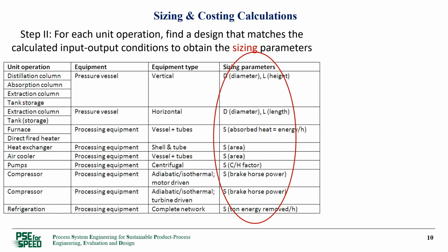So we need models then to calculate them. Some simulators give some of these design parameters. Usually the column diameter and length can be obtained as a rating calculation after the simulation.